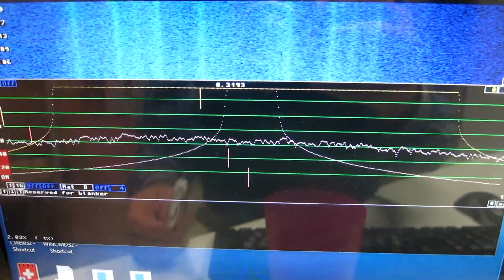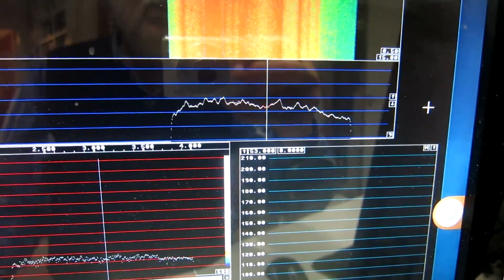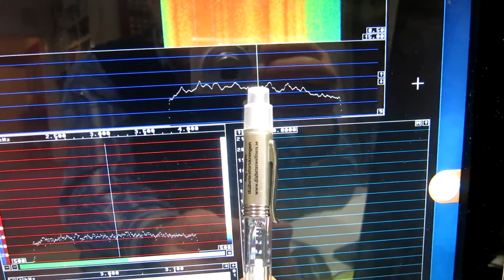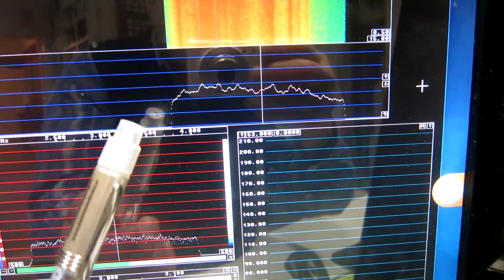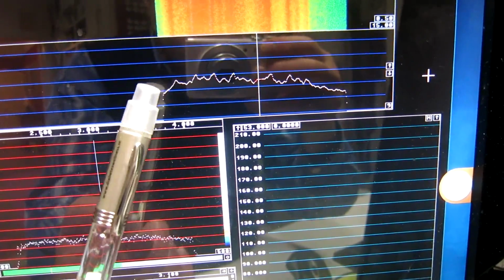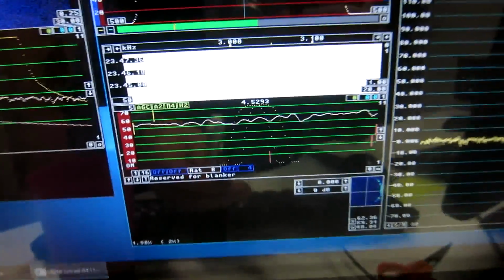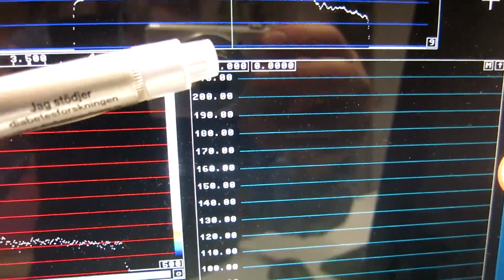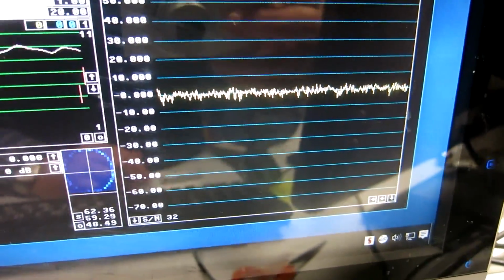to here, and I'm sending that into a second instance of Linrad where I do the signal to noise measurement, and I have selected a frequency at the center where the noise power is more or less the average of the noise power in the total 2 kHz width. I set the filter to exactly the same bandwidth, it's the same sampling rate, and I have fed the same number into here, and I then read 0 on the signal to noise graph.